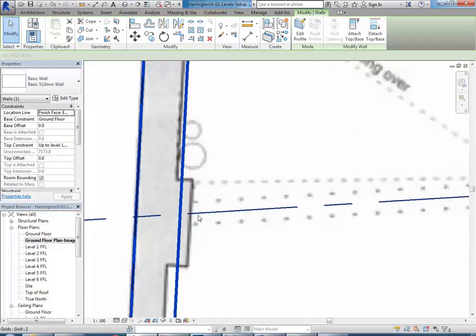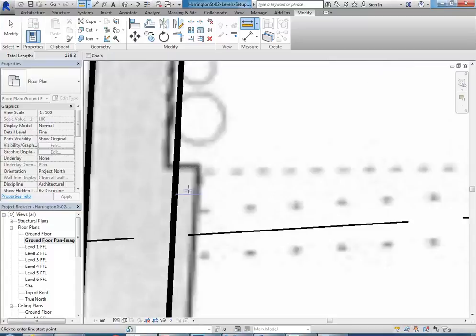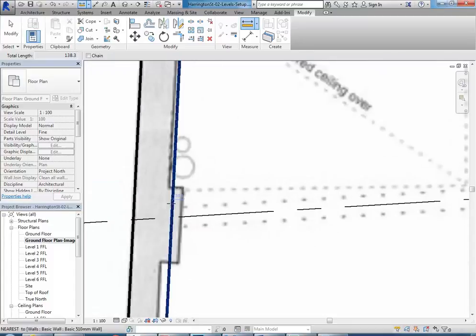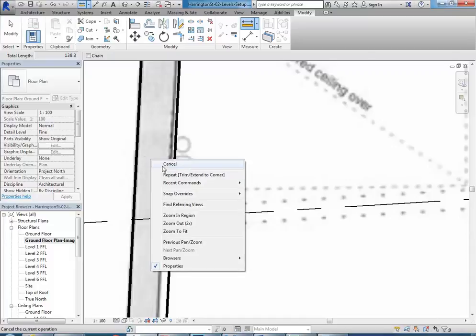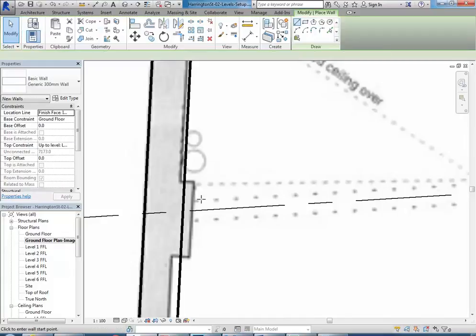And so for that, the best approach I find is to make a new wall. So you can see there the distance is 130. That again I think is just inaccurate drawing. So the pier would generally be 120 or 110 because that's a brick thickness, and then it may have the mortar as well. So okay, I'm going to go and make a new wall type.